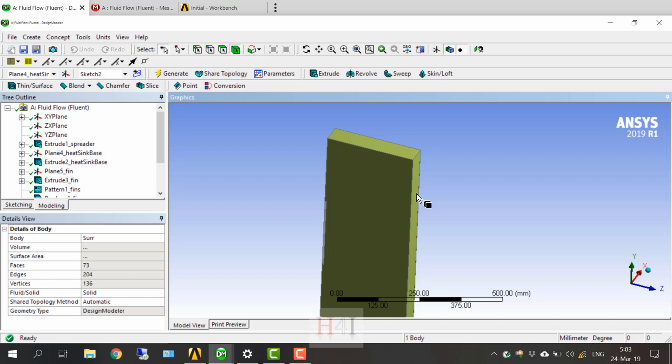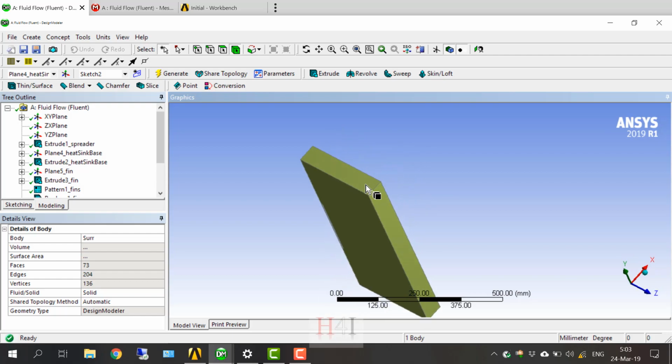What the dimensions should be is theoretically infinity. But I use some thickness and then enlarge this size further. This is 60 millimeter. I should study 70 millimeter, then 80 millimeter, until I reach a point with no change in results. So theoretically it should be infinity, but I use a very large dimension and increase it further until I find that it is not affecting the result.